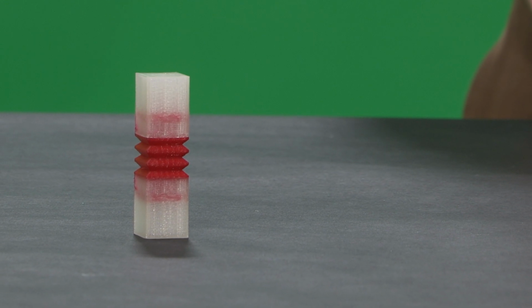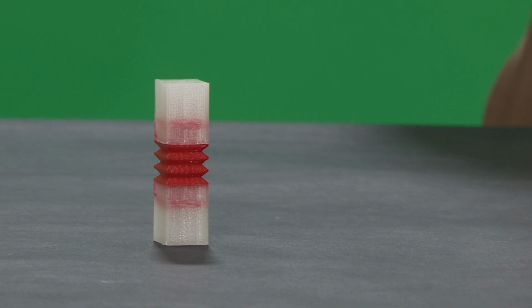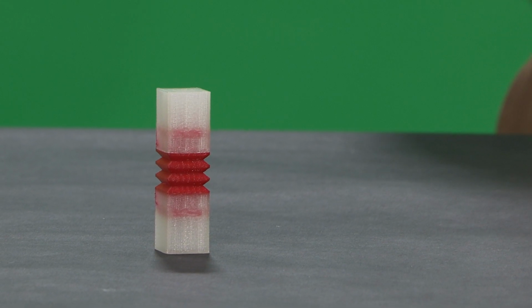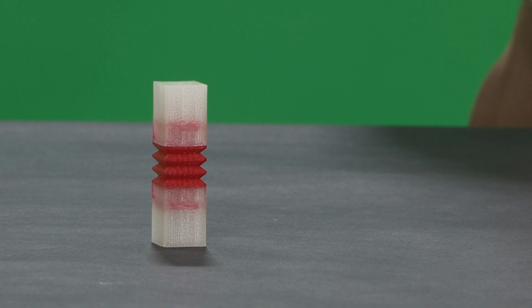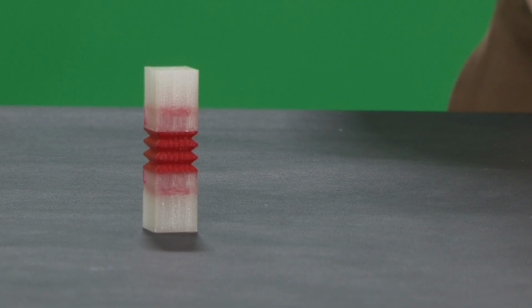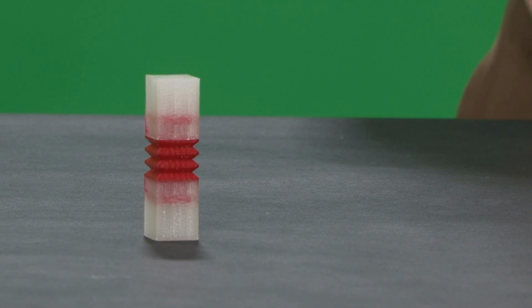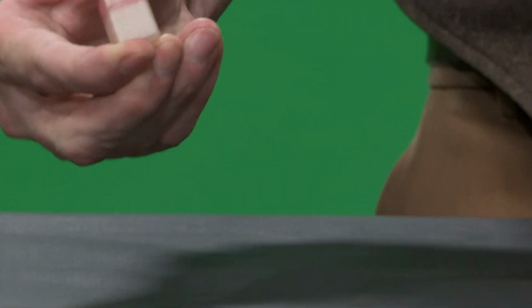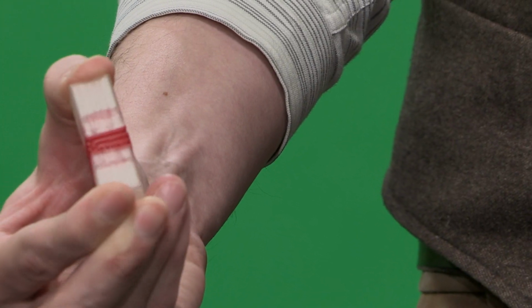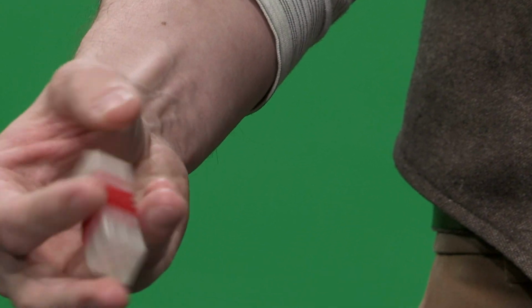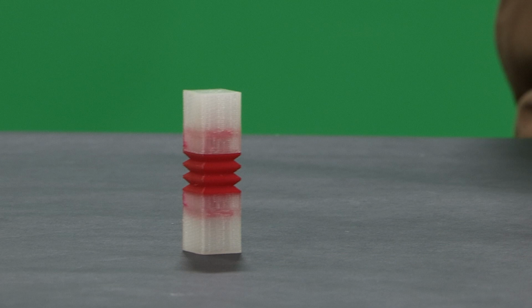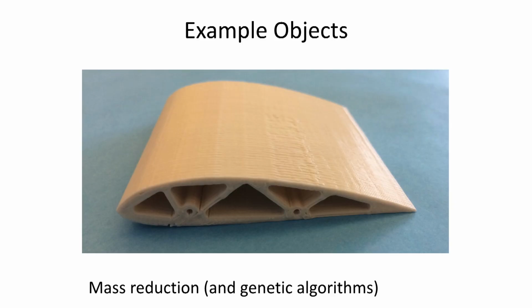You may have already seen prosthetic joints being produced, prosthetic hands being produced by individuals with 3D printers. And just adding a second extruder allows us to combine some different materials in one and make these interior parts. We could even make custom gaskets or make this hinge fully inside of a part where it would be very difficult to manufacture it. Additive manufacturing, once again, because it can leave interior spaces wherever we want, not just in terms of infill, but in terms of the structure, the shell structure itself right here, also lets us reduce mass on objects.